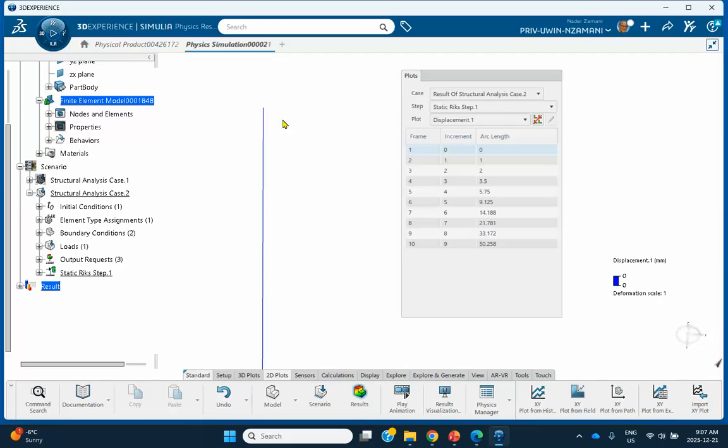Now you can't see it because it's a thousandth or a tenth of a millimeter, and the deformation scale factor is 1. If I had used, for example, 10%, you would have seen that this initial one would actually be way further to the right. We'll see that.